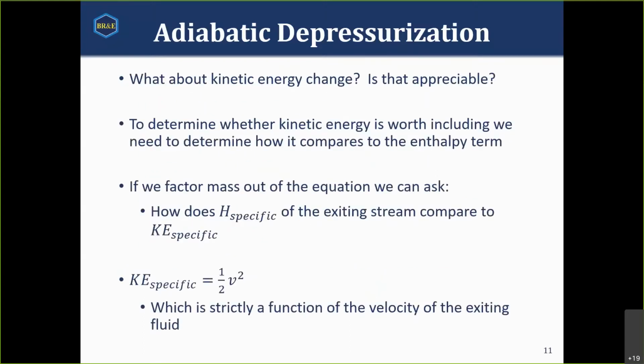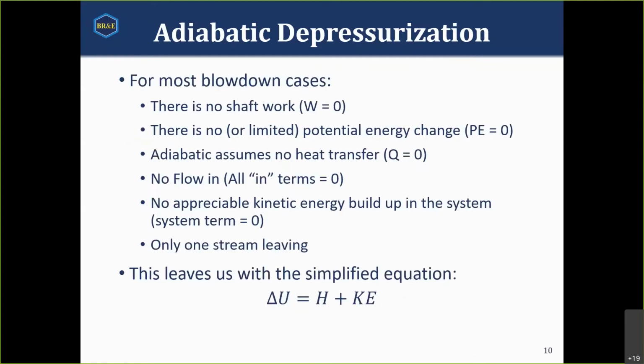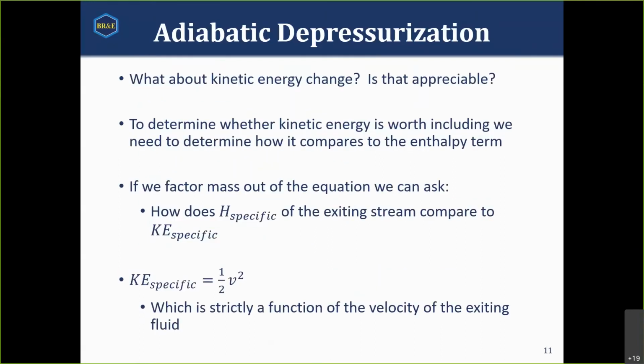To determine how much kinetic energy there is and whether it's worth including, the important thing isn't whether kinetic energy has any sort of value, because it does. It's whether that kinetic energy term is comparable to my enthalpy term. If my kinetic energy term is small compared to my enthalpy, I can ignore it and say it's irrelevant. So let's look at it and compare it to our enthalpy.